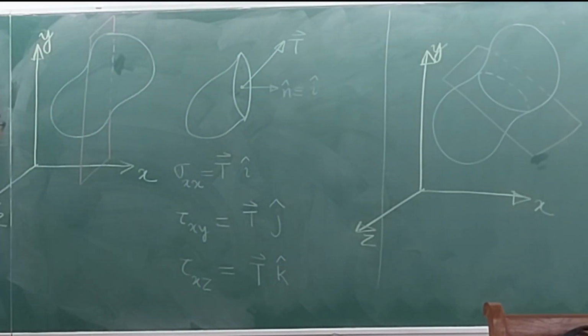Okay. Yes. But in that example we saw that as area tends to zero, the moment should be zero, right? Right. But here, if you take a moment about, let's say, the center of that exposed plane. No. Not that moment. It has to be the moment within that area. Because when you are doing this, your entire universe has shrunk to this. Then don't worry about the rest of it. This is the general distribution of forces you have. Okay. So the axis has to be within it.